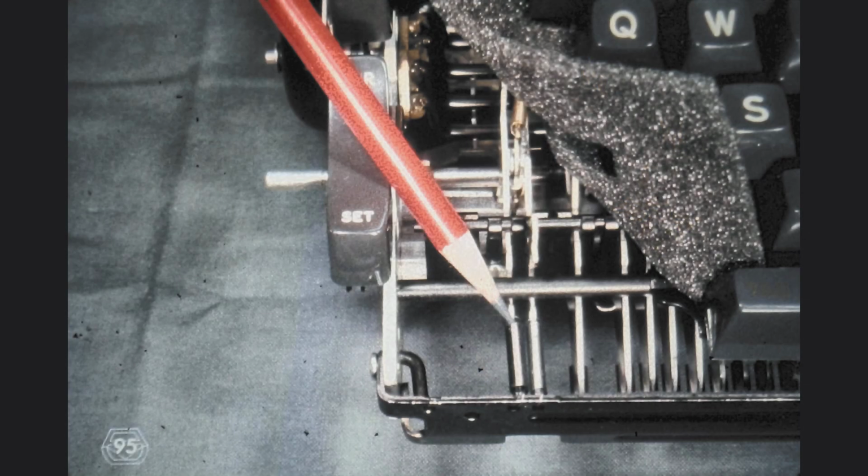On the left-hand side of the keyboard, the tab keylever was also affected by the keylever up-stop adjustment. As you trace the tabulation keylever connection to the tabulation torque bar, you will find that all of the parts, including the torque bar, are restored and held in their rest position by the indicated tab keylever restoring spring.